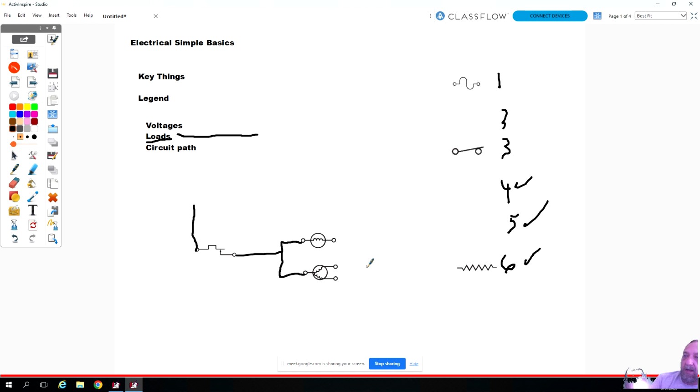Because when they're telling you it's not draining, it's not filling, it's not heating, it's not pumping, it's not spinning, we need to know, okay, if it's not draining, got a drain pump. Where's the drain pump? So I want to find that load inside the diagram. This could be a pump. It's just a motor. I could call it anything I want. Condenser fan motor, drain pump, or whatever.